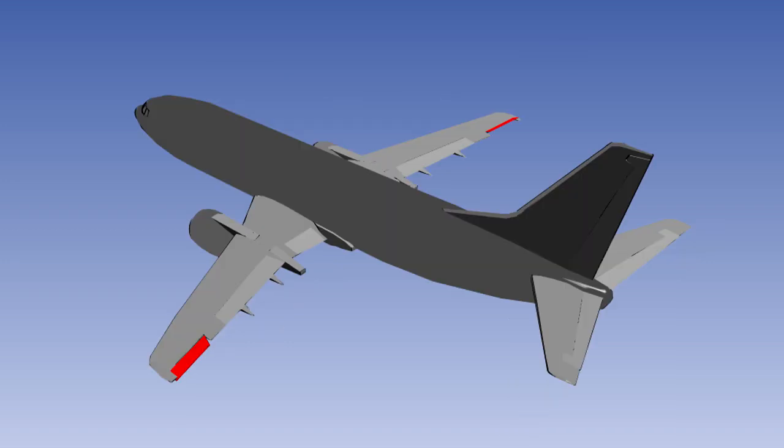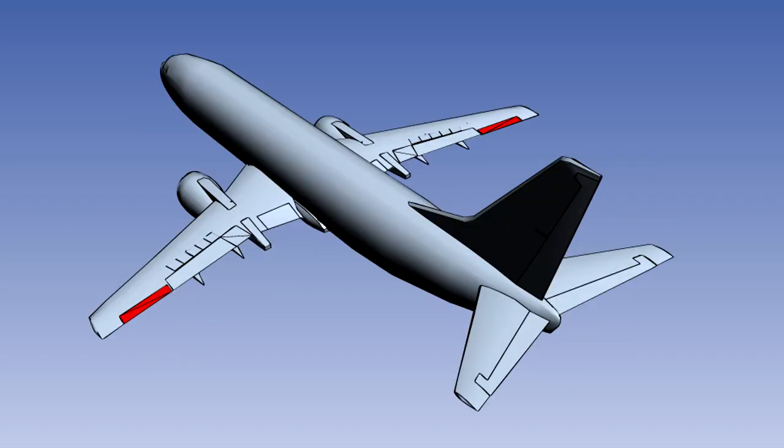The ailerons are normally situated at the wingtip to give the greatest moment for the force produced. However, this also means that they cause the maximum twisting and bending loads on the wing. As the aircraft speed increases, this can cause a loss of effectiveness, or even reversal of the aileron. To reduce these effects, the ailerons can be mounted further inboard.